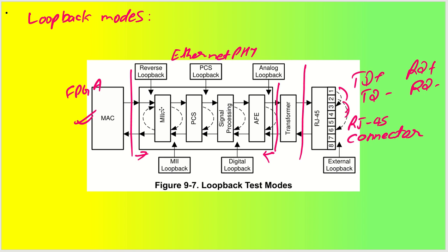This is very much used because we don't want to send the signal to the outside network while testing or debugging our design. So in that case loopback test mode is very useful. As you can see, we will be utilizing one transformer in the middle, a 1:1 transformer, which will be used as an AC coupled signal or isolation signal. AC coupling is basically done by putting a capacitor here. If you do not need the isolation, then you can utilize a capacitor.